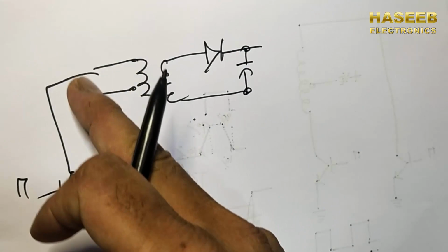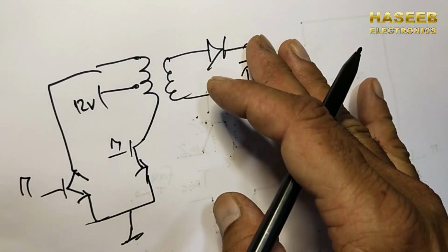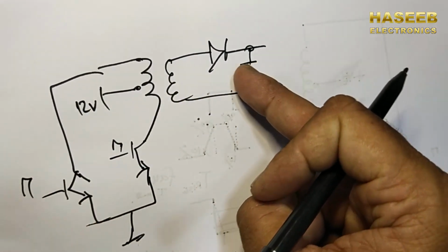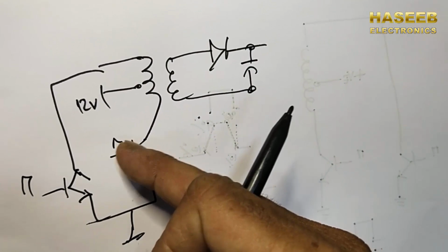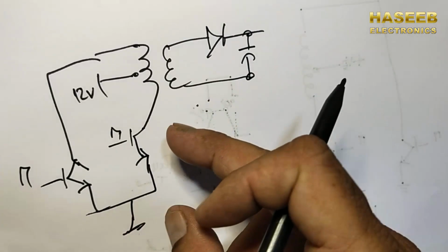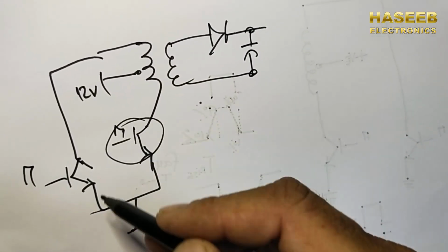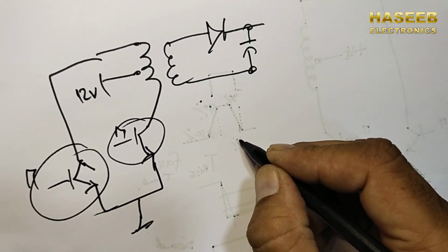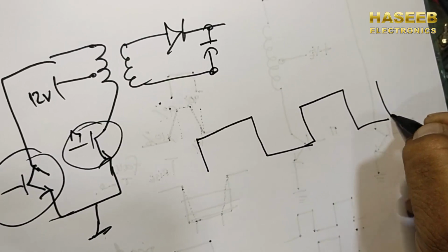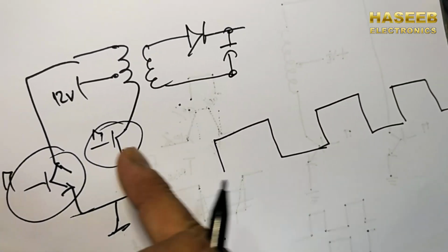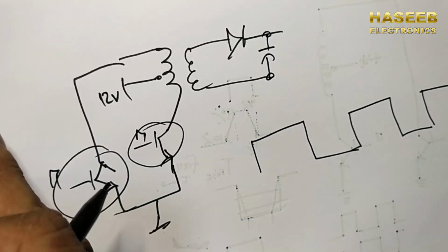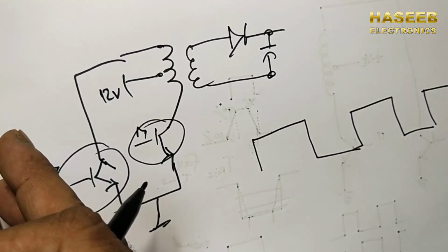When this circuit is dead, it is totally off, this capacitor is empty, and we turn on these MOSFETs immediately, it will generate a surge on this MOSFET. It will cause a full current to flow. So to protect this MOSFET from full current, if we turn on at this cycle, it can damage the MOSFET, or it can damage the rear circuit, which is the DC rail and bridge rectifier and